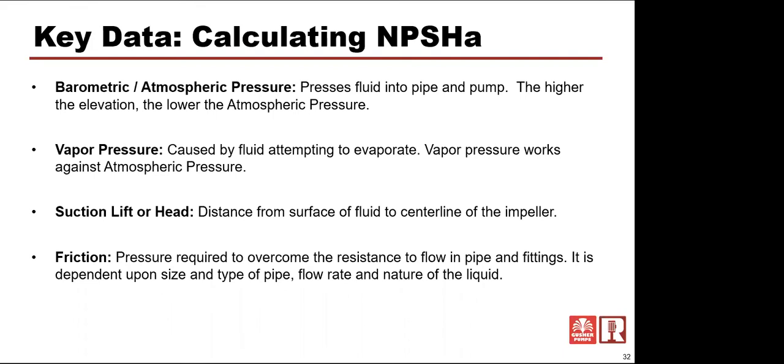And the other thing that comes into consideration there is pipe friction. If we have a pump mounted right underneath the tank with 3 feet of pipe, it's generally not too much of a concern as long as that pipe is sized properly.